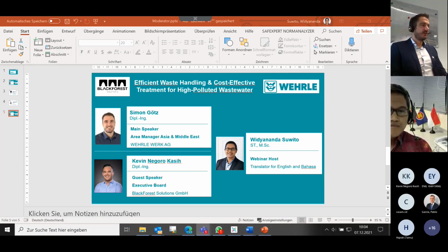TKN contains ammonia and inorganic nitrogen. And usually in the leachate, most of the TKN, let's say 95%, is ammonia. And this ammonia in the nitrification tank gets oxidized first to nitrite, NO2. In the second step, still in the nitrification tank, from nitrite to nitrate, and then it gets pumped back to the denitrification tank, where it gets denitrified from nitrate into elementary nitrogen gas, and that leaves the reactor. So that is one main purpose and one strength of why the MBR unit, for example, can handle up to 7,000 milligrams of ammonia in the leachate.